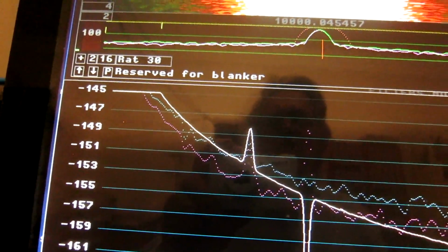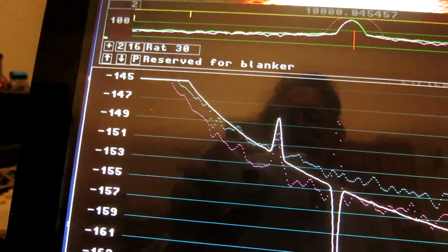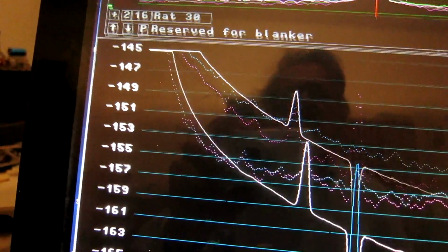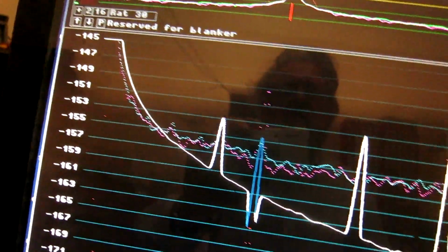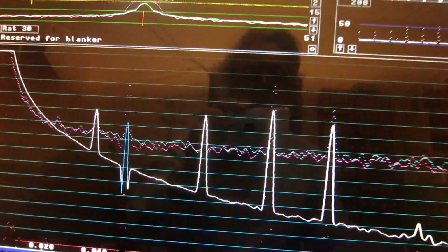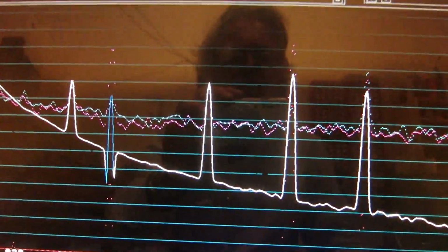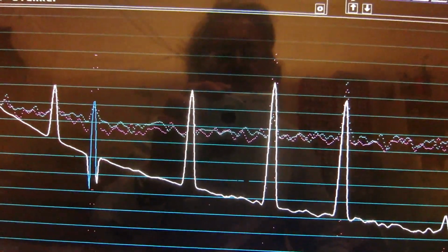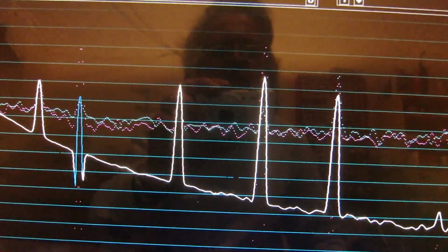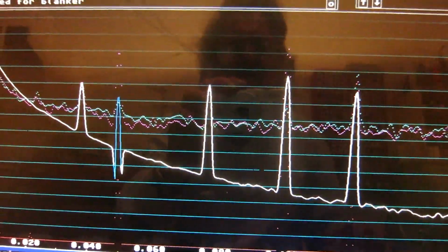And the amplitude noise is strong enough to be visible in the power spectra, not only in the correlation spectrum. So something happened to the power amplifier, something that produces AM noise, but not on the limited output, because that is now very low in AM noise, and the phase noise is unaffected.